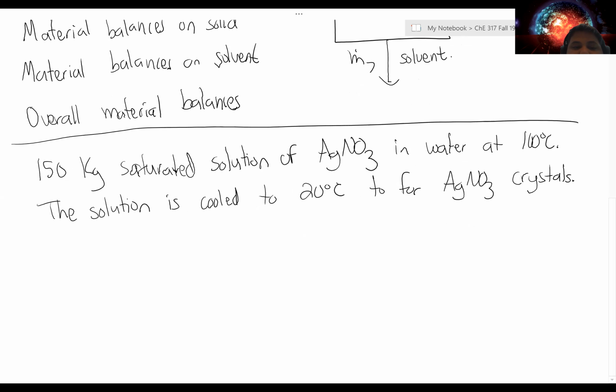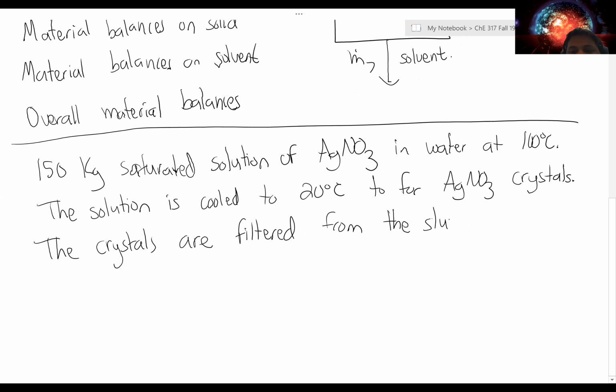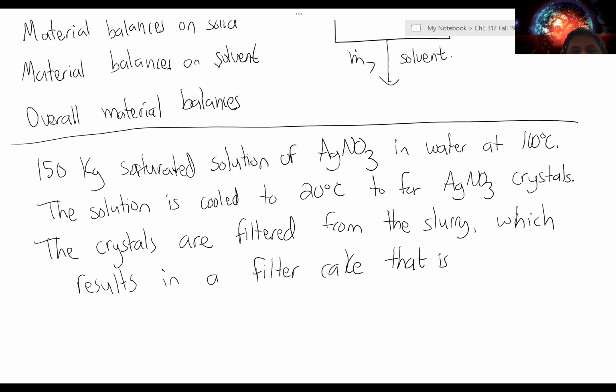So the crystals are filtered from the slurry, which results in a filter cake that is, I believe, 80% solid crystals and 20 weight percent, and I'm going to say weight percent to be more specific, and feel free to ask me those kinds of things.